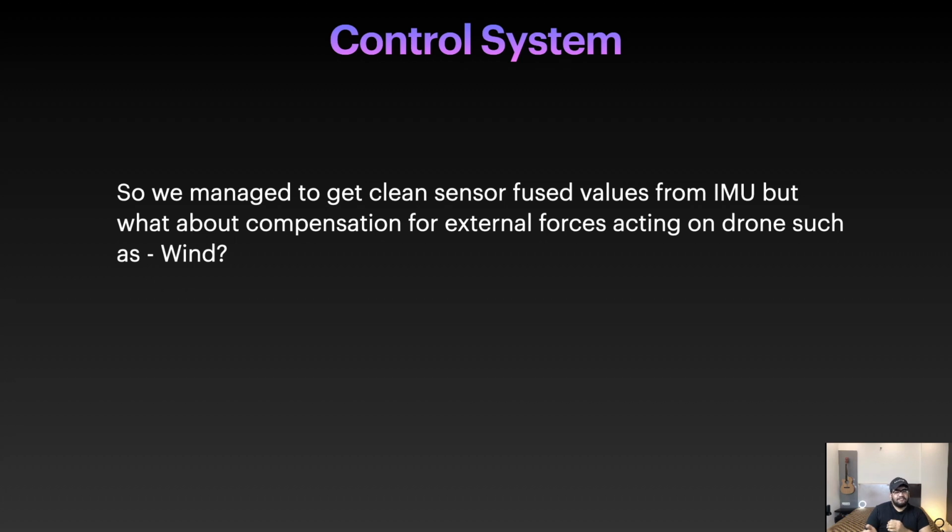Maybe some motor has more RPM than other. I'm not saying it would have drastically more RPM, but let's say 100 RPM more, because of, let's say, manufacturing defects, or it is a bit smoother. So these kinds of things are very, very common when you are doing some electromechanical system, some manufacturing process defects and some other things. Because of that, you just cannot achieve the exact system which you have designed or which you have simulated. So that is why you need a control system, and in this case, a flight controller.